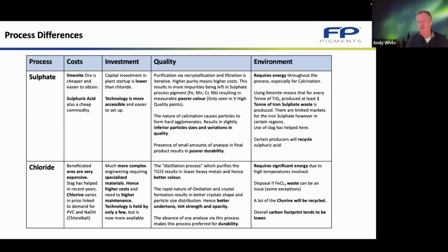Overall, however, the carbon footprint, when they do a cradle to gate of a chloride process, tends to be a little lower than the sulfate process, but the sulfate process plants, depending on if they have acid recycle or not, have significantly different titanium carbon footprints. The Titanium Dioxide Manufacturers Association has basically shaken hands and agreed on a single number of, I think, 4.9 tons carbon per ton TiO2. That is done from all types of titanium dioxide as an average. But the range is probably something like 3.2 to 8, depending on the plants.